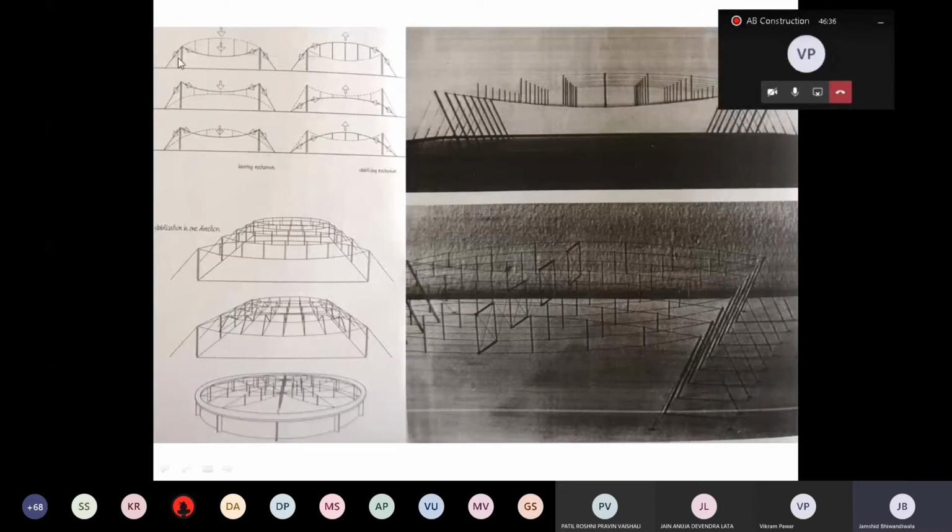So you get the idea: you use the span, you use the sagging of the member as a bottom boom of a truss, and create a kind of trussing member through perhaps less than 1/3 the material that you'd use if you'd be using a girder or a truss.